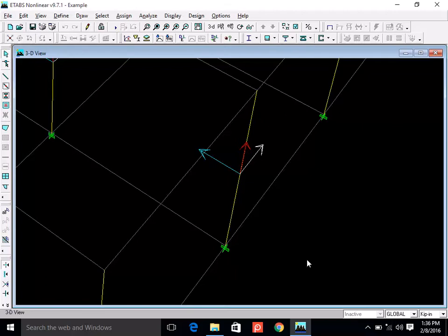thing, that corner columns have biaxial bending. Edge columns mostly have uniaxial bending. They may have biaxial bending if there is unsymmetrical loading, but not significant. And a column in the center which has tributary area on all four sides approximately equal will mostly have significant axial force but no significant bending moment. And if it is perfectly symmetrical, then theoretically there shouldn't be any bending moment, right?